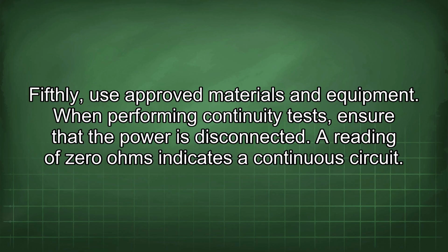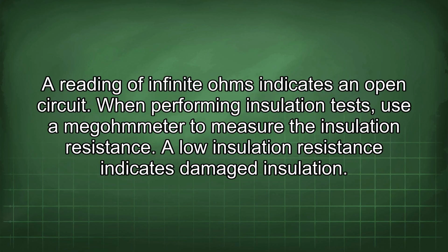When performing continuity tests, ensure that the power is disconnected. A reading of 0 ohms indicates a continuous circuit. A reading of infinite ohms indicates an open circuit.